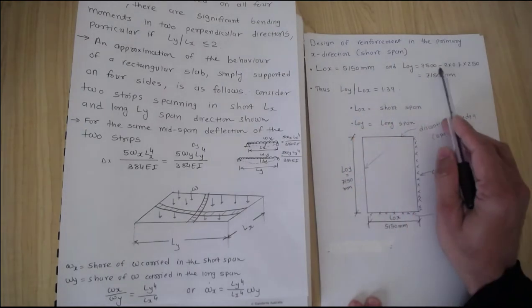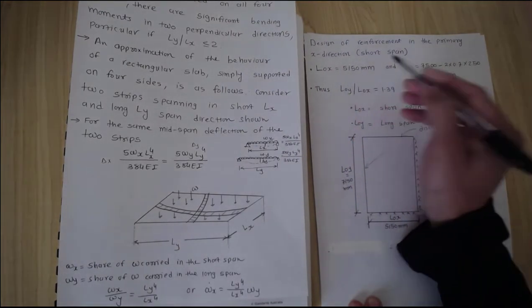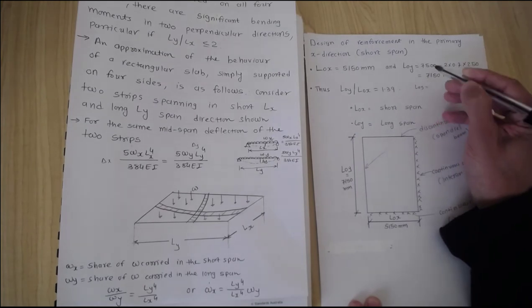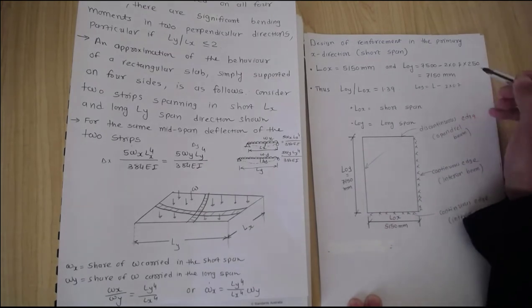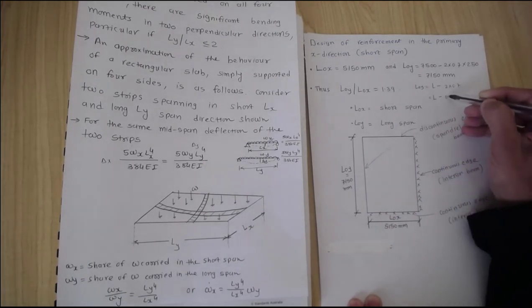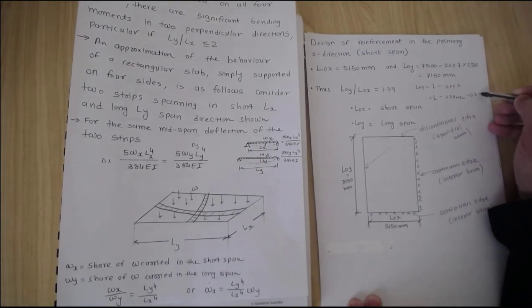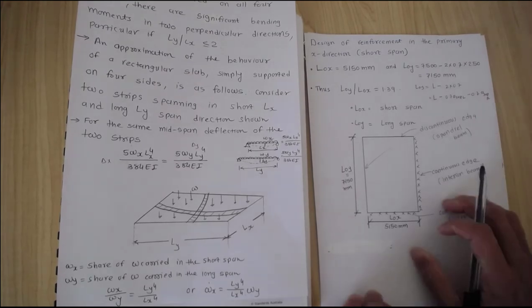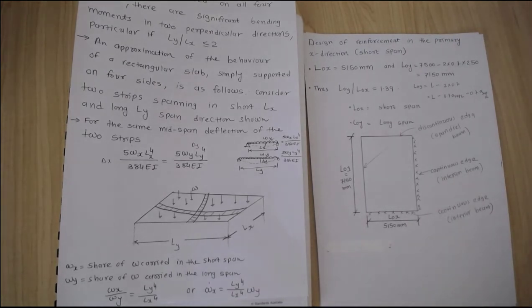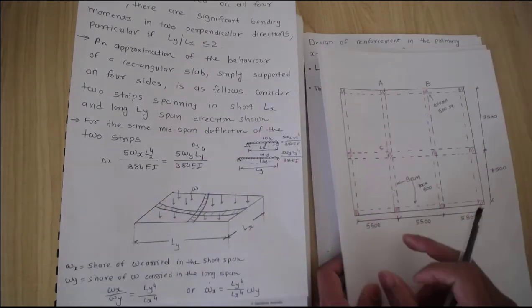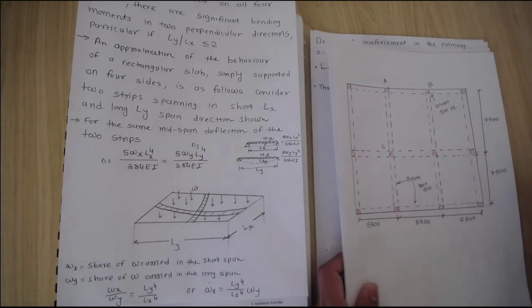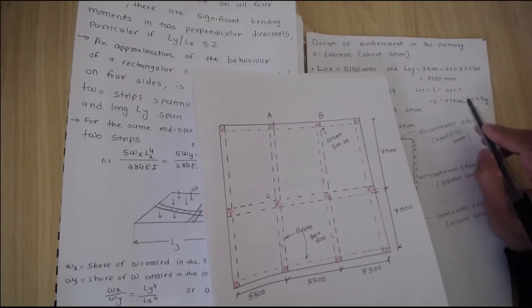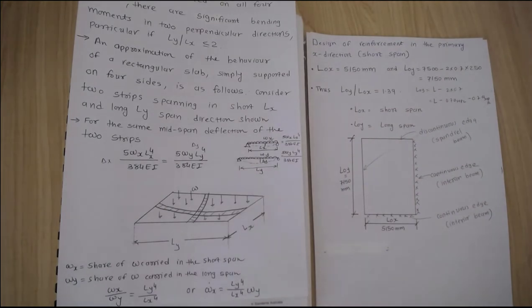Now, Lx and Ly we calculated previously. Basically, Ly is equal to L take away 0.7 A support on the left and 0.7 A support on the right. What are they talking about? In the last video we discussed that if you have this length, which is 7500, then A support is the half distance, which is 250, times 0.7 and 0.7, which gives me 7150.